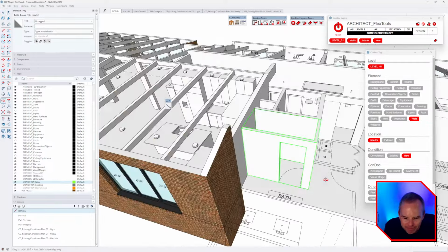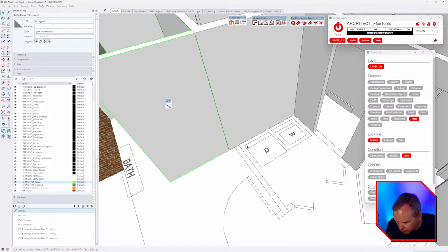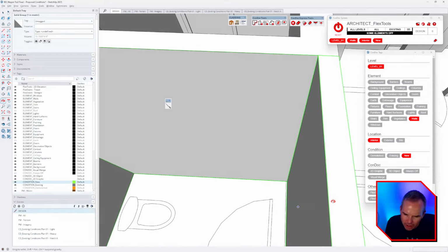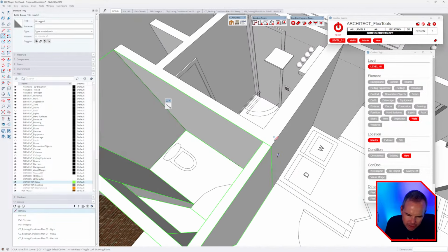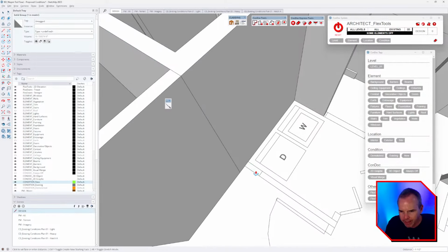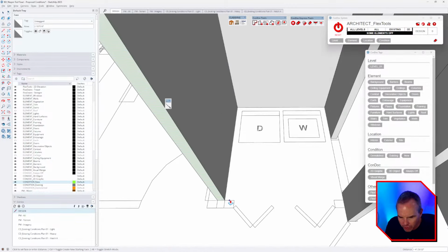So you can see we've effectively assigned multiple SketchUp tags to one entity. All right, so that looks pretty good. And then I'm going to draw another rectangle here. It does look like I made this 3.5, so I'm not sure what I had going on. I'm sure I was trying to address the connection from an existing wall to a new wall. But anyway, we'll go like this and pull this up. So that was a clean 3.5. And then I can pull this across.